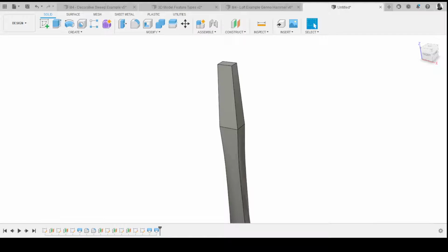Any idea how I'm going to join them together? What function shall we use? No, that's where they've got a mechanical relationship and you want to have motion. You want to turn them into one body: combine. Yeah, because if you think about the wooden handle of this, it's going to be one component, isn't it? One thing. So under Modify, Combine.